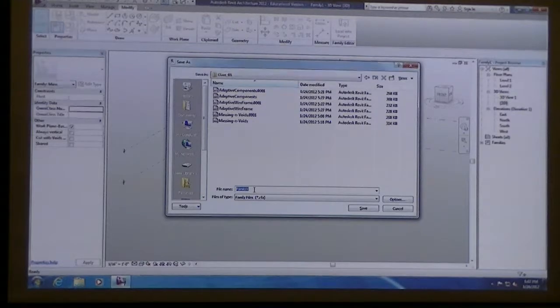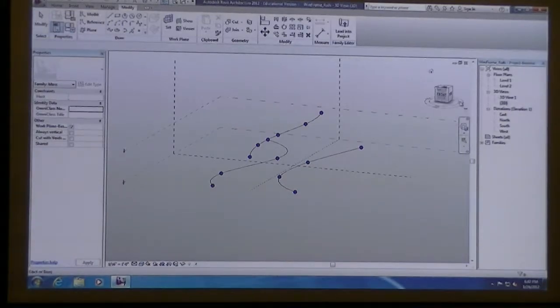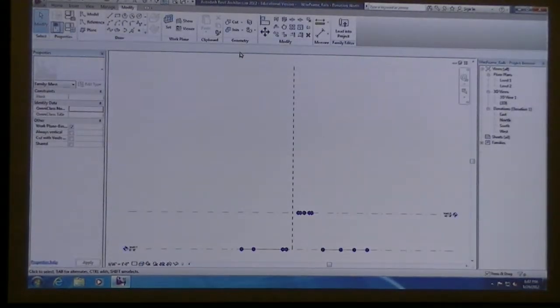Jeremy, whenever I set a new level datum, it doesn't create a new floor plan level. Mine just won't create a new one. Or it'll show that there's a new level there, and it'll let me make one, but it doesn't reflect in the project browser.